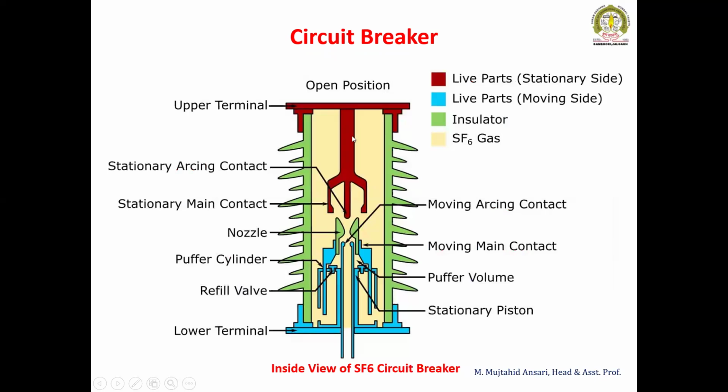So this is the circuit breaker. A circuit breaker is nothing but a device to open the contact in the live part, but it is going to operate automatically and in the on condition. Whenever a fault is going to occur, the relay is going to sense the fault condition. It will give the command to the trip circuit, and the trip circuit is going to close the contact which will open the circuit breaker contacts. Means there are circuit breaker contacts and a tripping circuit. The tripping circuit is the control circuit, whereas the circuit breaker is going to close and open the power circuit.